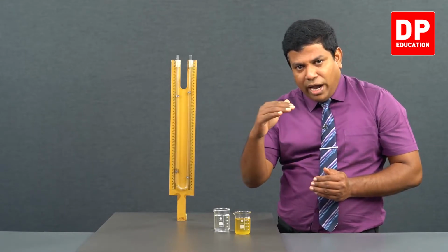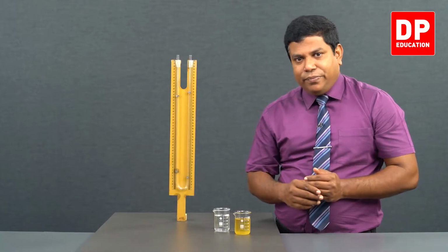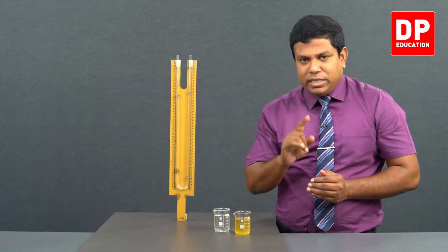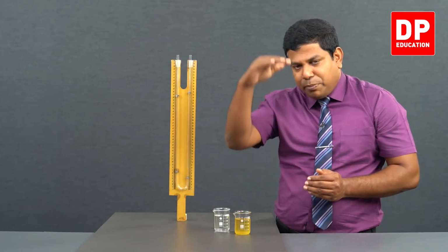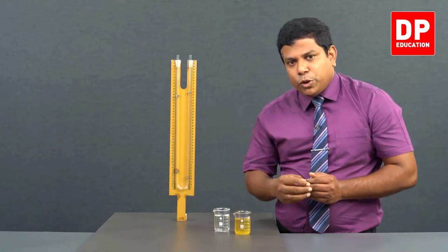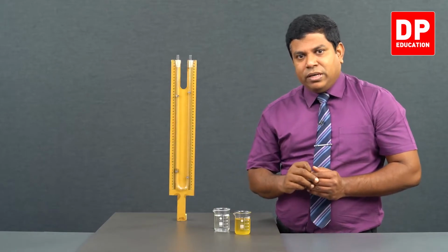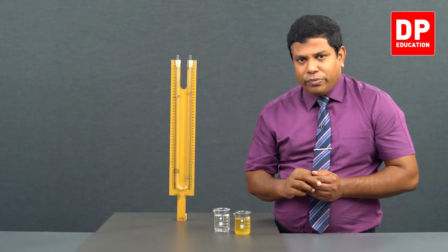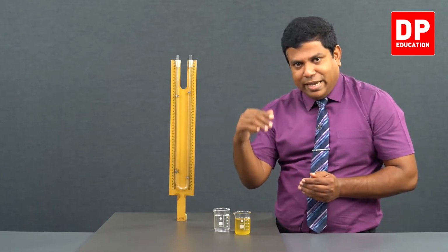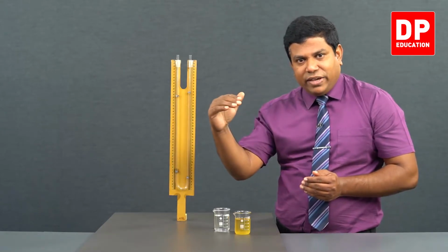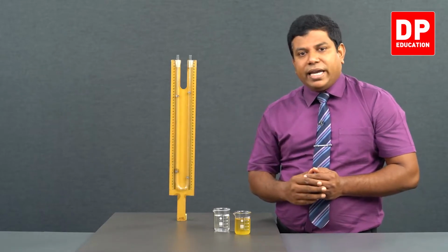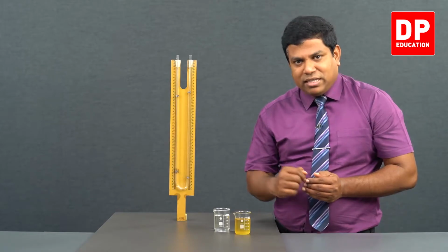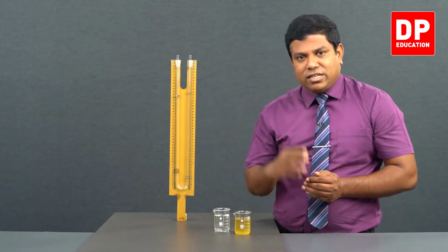At the same height, if you move on to the other side, below what we have is water. Pressure has to be same. Above that point, what you have on the other arm of the U-tube, it's just the water only. If I find the height of that water, let it be H_W, then the pressure at the same point as the water-oil interface, on the other arm at the same height, we can say is A atmospheric pressure plus H rho G of water, H_W rho_W G.